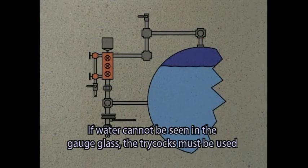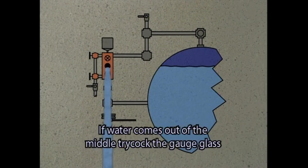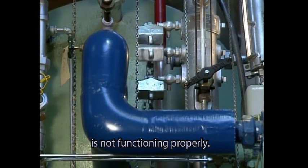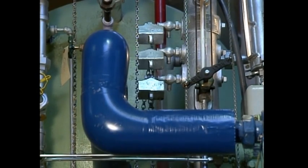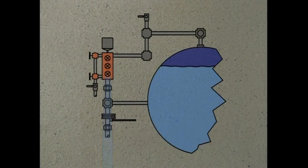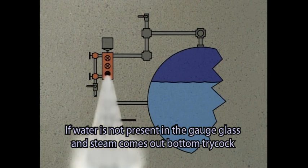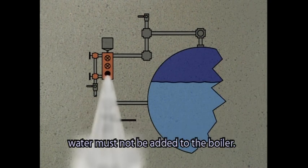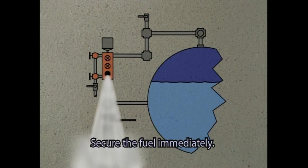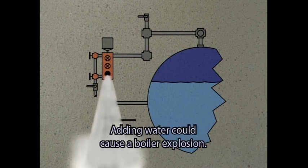If water cannot be seen in the gauge glass, the tricocks must be used to determine water level. If water comes out of the middle tricock, the gauge glass is not functioning properly. If water comes out of the bottom tricock, water may be safely added to the boiler. If water is not present in the gauge glass and steam comes out of the bottom tricock, water must not be added to the boiler. Secure the fuel immediately. Adding water could cause a boiler explosion.